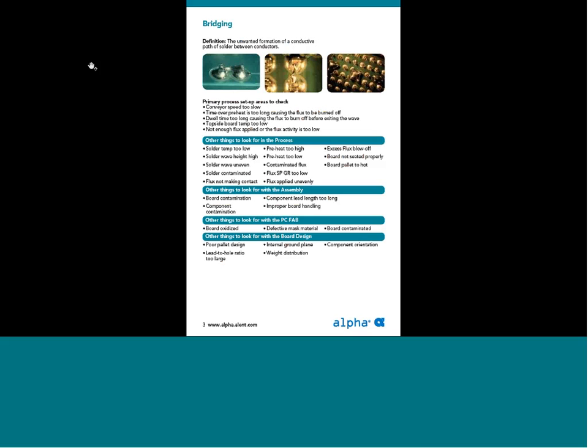You not only need to look at your process, but you need to look at your assembly. Is your pin-to-hole ratio correct? Are the ground planes properly thermally relieved to allow a wave soldering process?